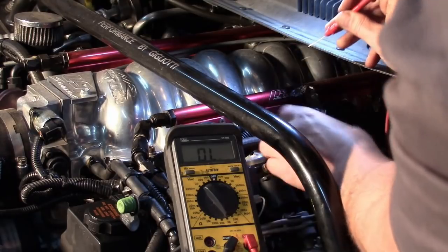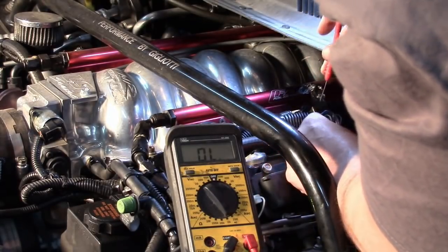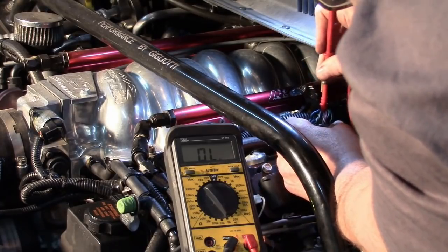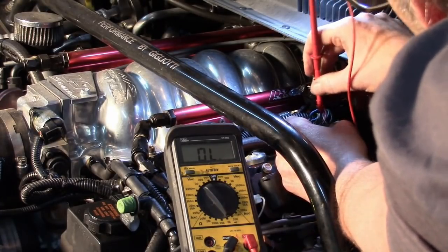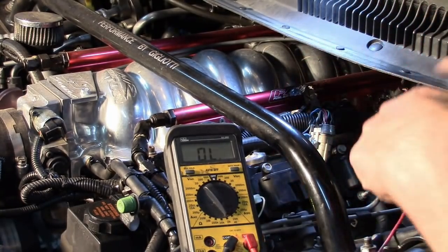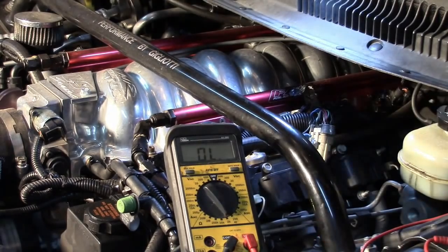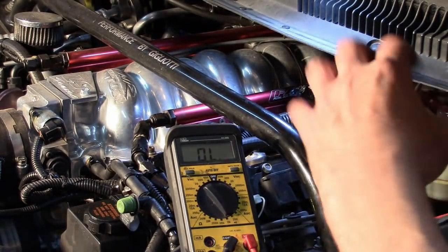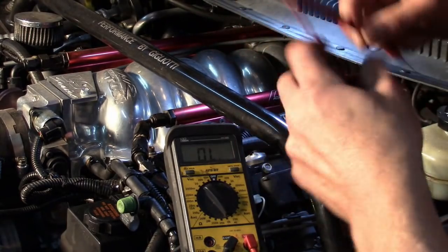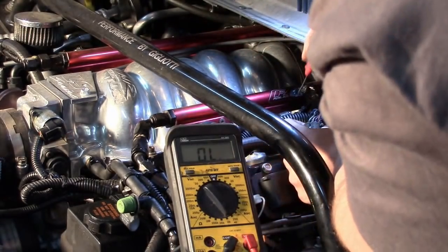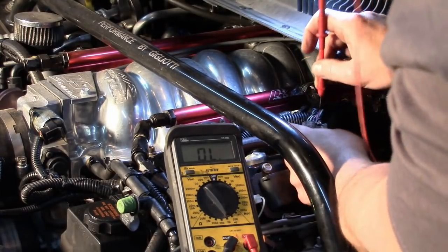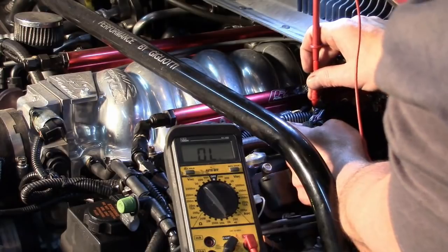One of the things, it's possible I could find a ground through one of the signal wires if the engine happens to be in the correct position and the cam and crank signal is calling for that coil to be grounded. So it is possible I could find it. I can tell you, given the thickness of this wire, I do believe the black is going to be the ground. Now, there's a way that I can verify that, and that is,